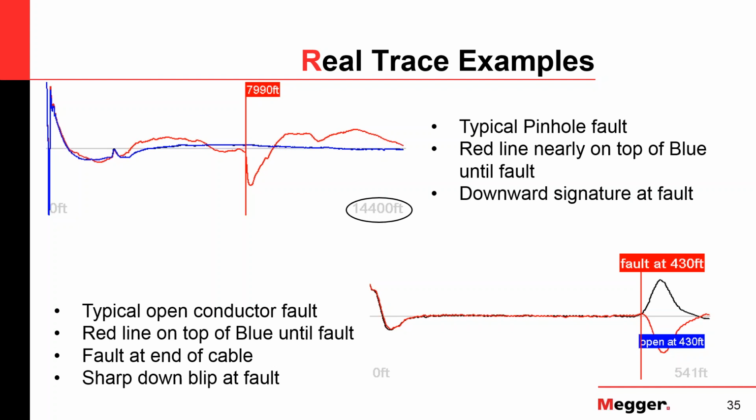Well, I think, yeah, I agree with you. I would think it has to do with the cable velocity, because it's really the factor that the pulse travels along the cable. I think that would be my interpretation. Typically, people refer to it as velocity, or propagation velocity. But I think runtime factor is pretty much the same, because it tells you how long it takes for the pulse to run back and forth on your cable. So I would agree with you. It's cable velocity. I think that's what it's referring to. Okay.